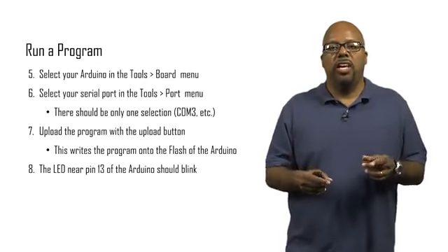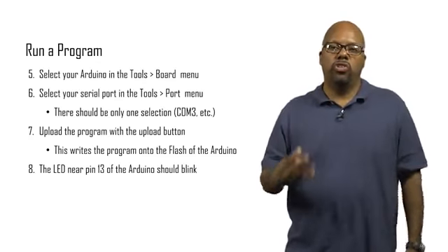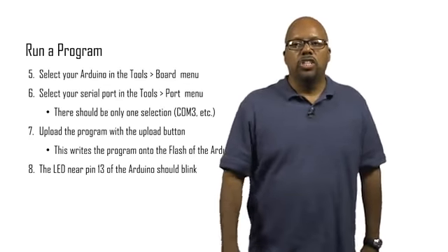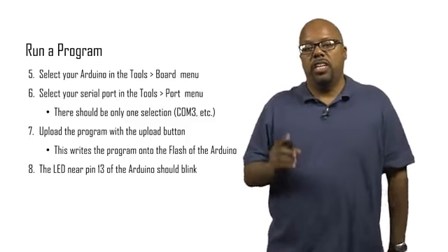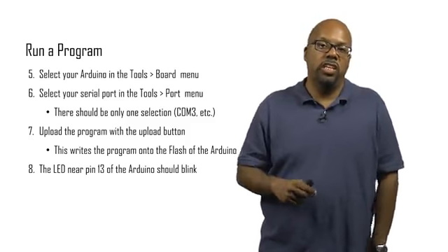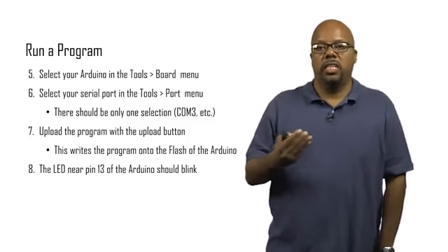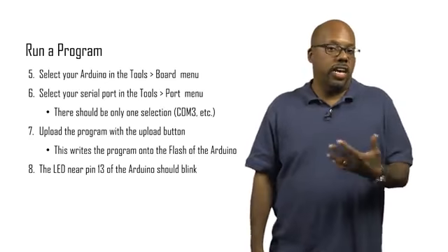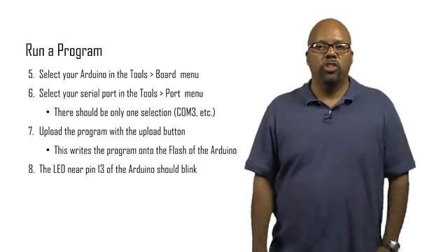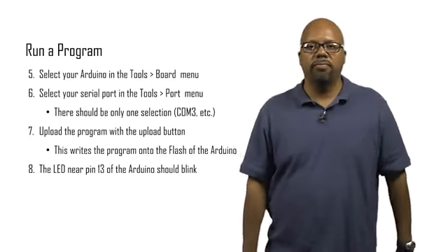As soon as it's done uploading, the Arduino will start executing the program. What should happen is there's an LED on the board next to digital pin 13, and it should start blinking once every second. If that happens, then you know that your install is right and everything's working. So you should do that as soon as you get your stuff.